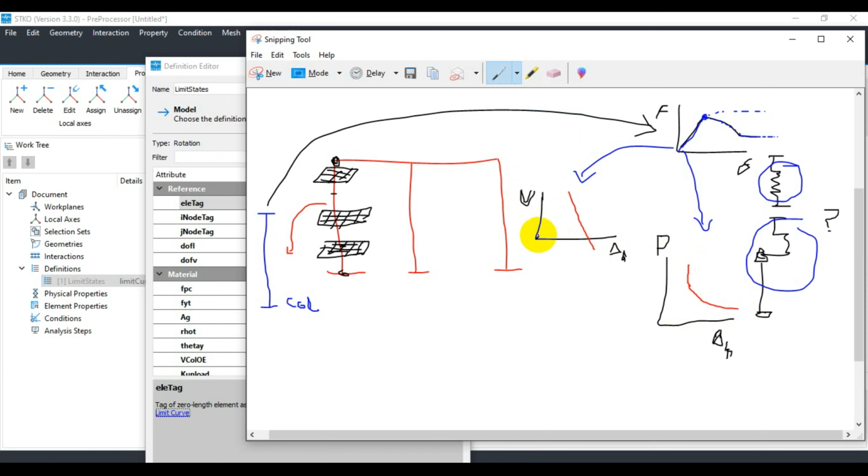And at a certain point, the shear is increasing in its elastic range. Then plastic deformation occurs, and after a certain amount of plastic deformation, this region is trimmed from this model, and this will be considered as the total failure of this model in terms of shear.